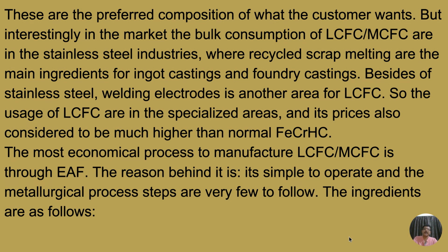But interestingly, in the market, the bulk consumption of LCFC or MCFC is in the stainless steel industries, where recycled scrap melting are the main ingredients for ingot castings and foundry castings. Besides stainless steel, welding electrodes is another area for LCFC. So the usage of LCFC is in specialized areas, and its price is also considered to be much higher than normal high carbon ferrochrome. The most economical process to manufacture LCFC or MCFC is through EAF.